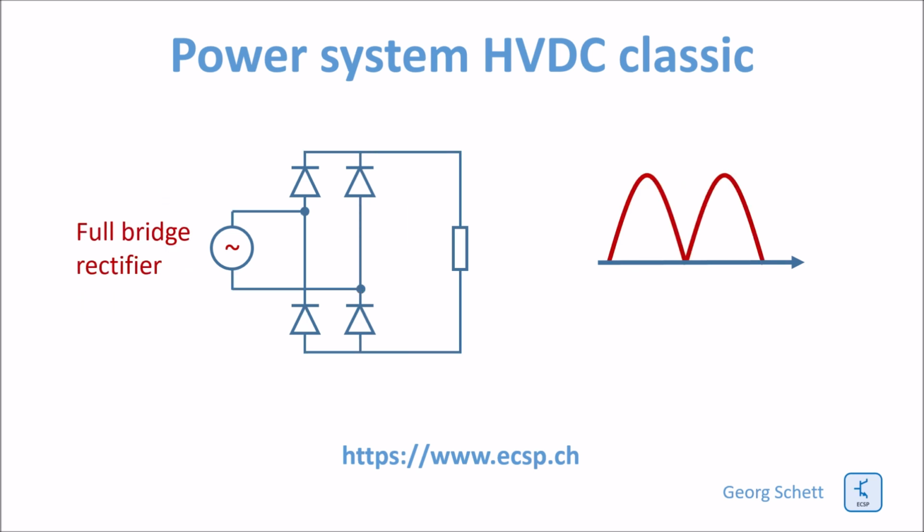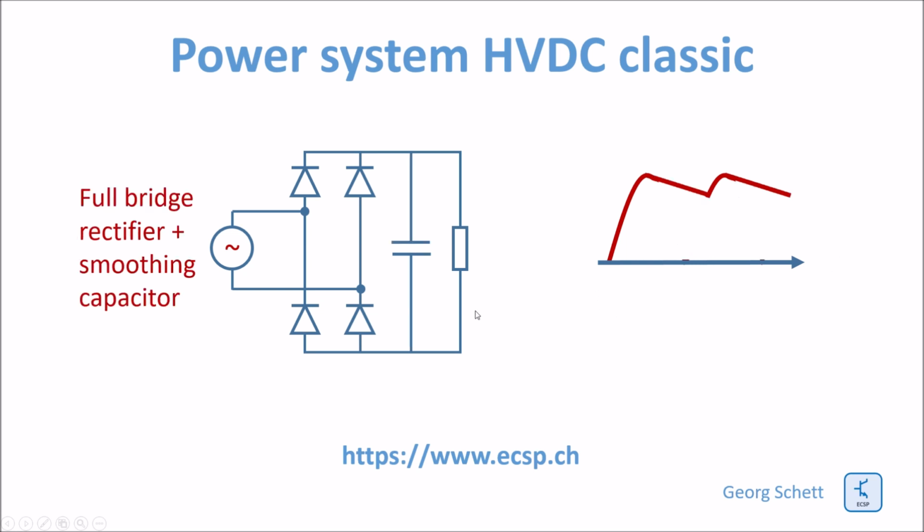You note that the DC here with this simple rectifier is quite bumpy. So in reality that would create a lot of noise. So you can connect a parallel capacitor to the load so you can smoothen the DC current or voltage. That will reduce the noise.